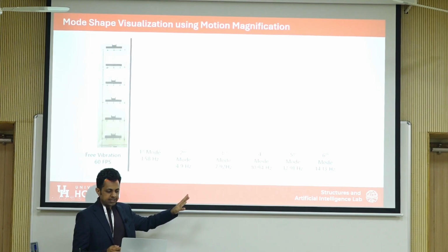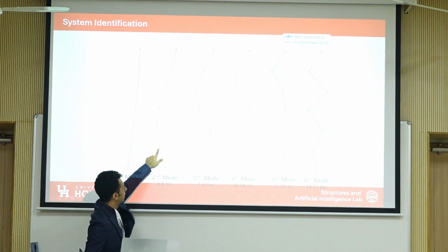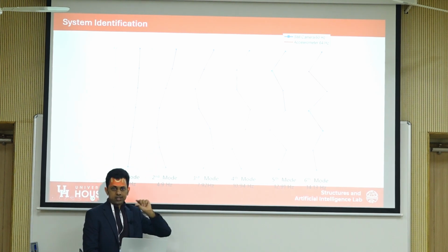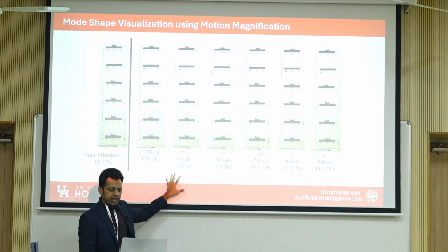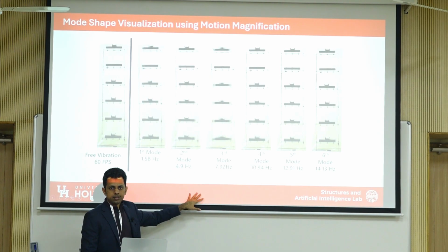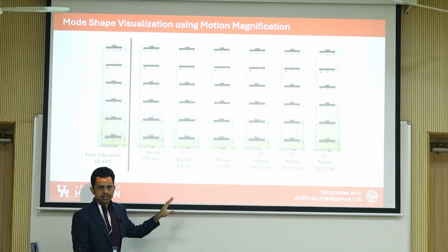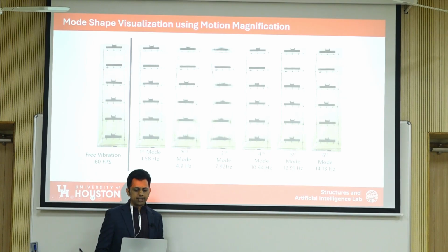In the previous case, I have a discrete mode shape. I have measurements at the floor points because those are the boxes that I selected. But here you can get something called a full field measurement of the displacement at different frequencies, and then you can reconstruct that into the overall displacement.